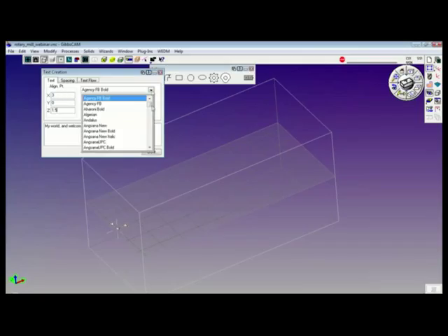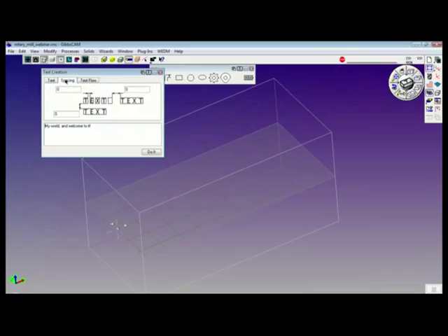The font, without getting too creative, we'll just find something. Arial bold italic looks good. The grid in the center, and my letter height 0.75. Central alignment, my spacing 0, 0, uses the parametric spacing of the font to space the letters.